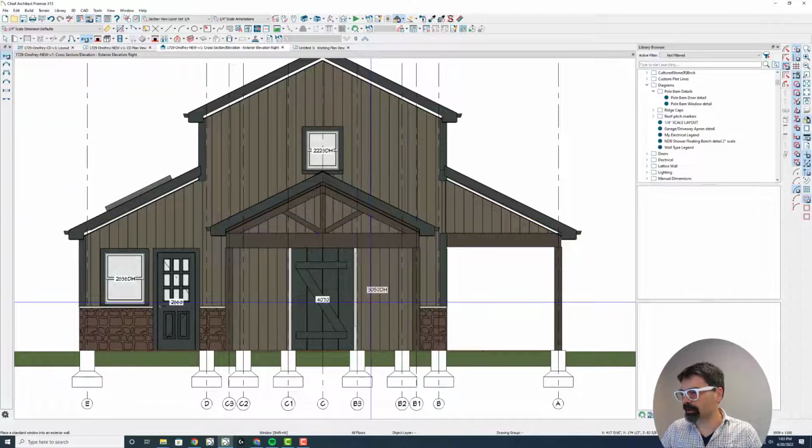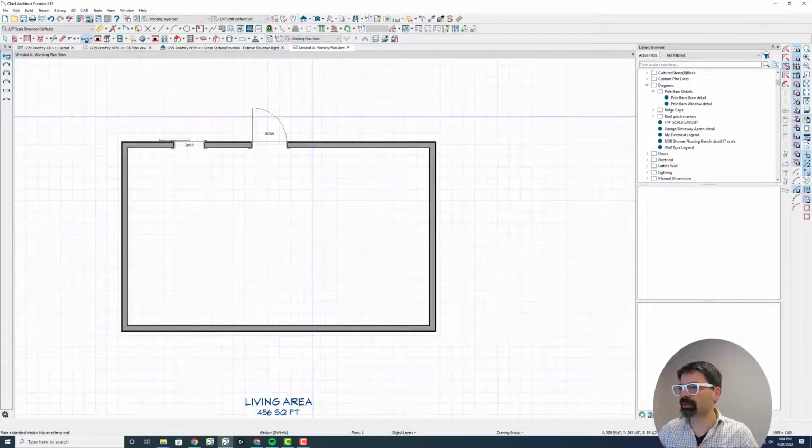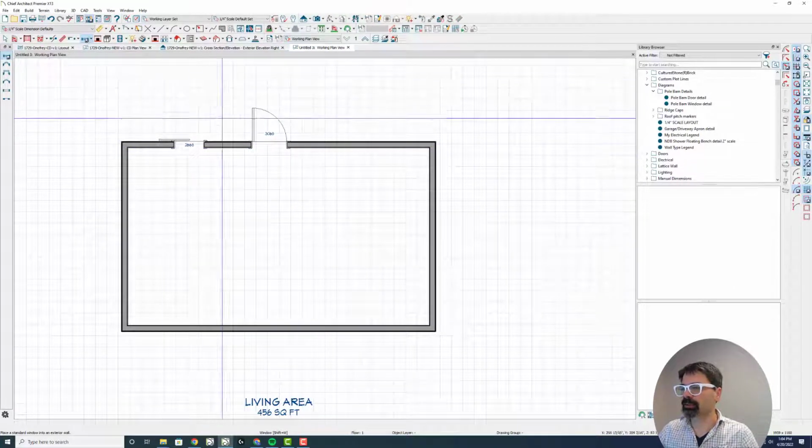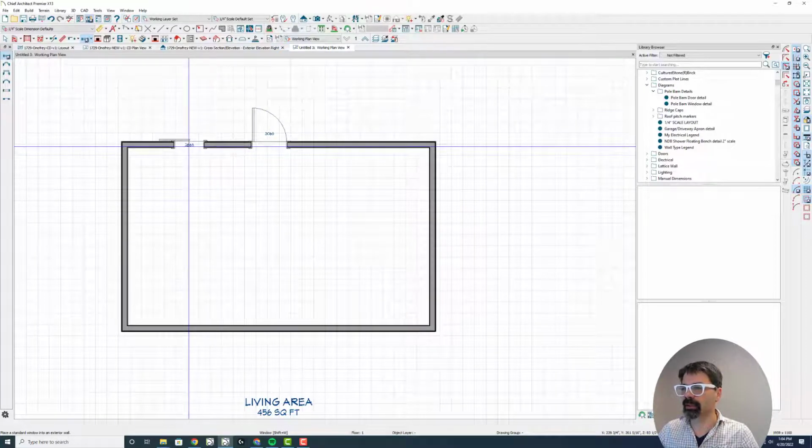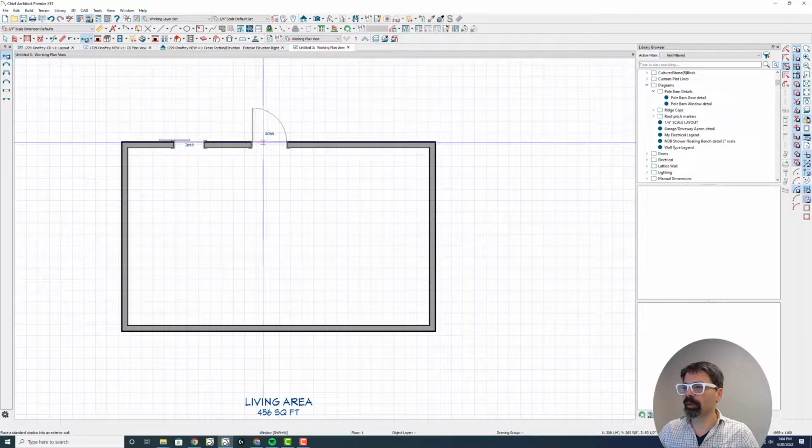On this barn door, I want to show an arrow right here. On these double hung windows, I want to show arrows that slide right here. Now, as I said, in X13 we can show that. By default, the template does not show opening indicators on sliding doors and sliding windows, but I'll show you how we can do that.